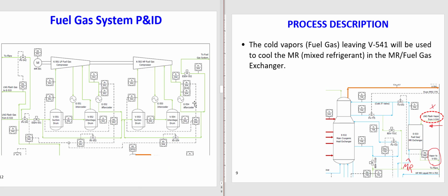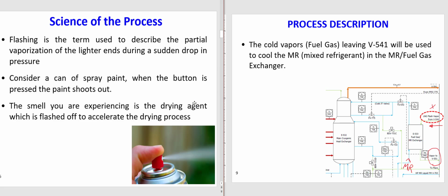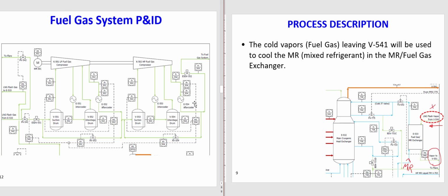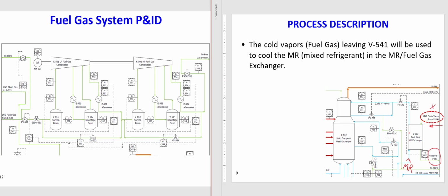So let me go back again to this slide. Okay, so let's continue here. Now this vapor, the cold vapor that is leaving the flash tank, the cold fuel gas, will be used to cool down the mixed refrigerant in this heat exchanger.